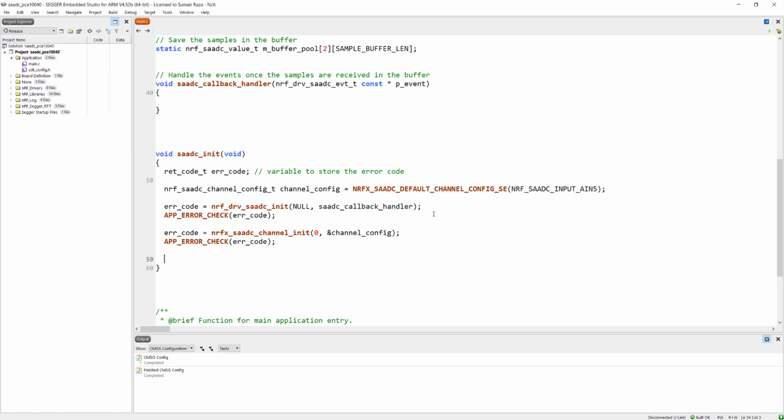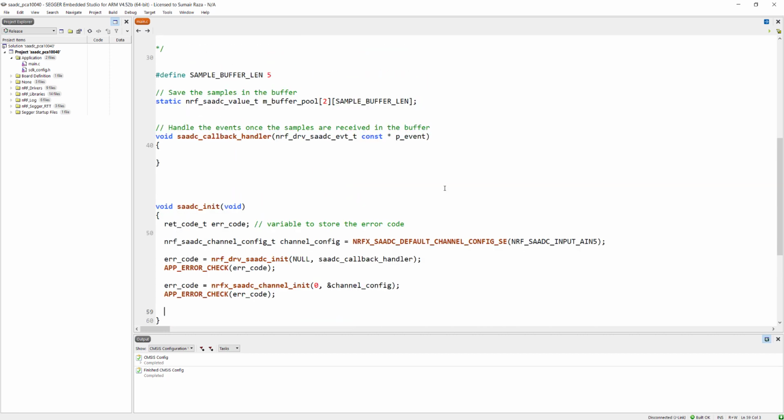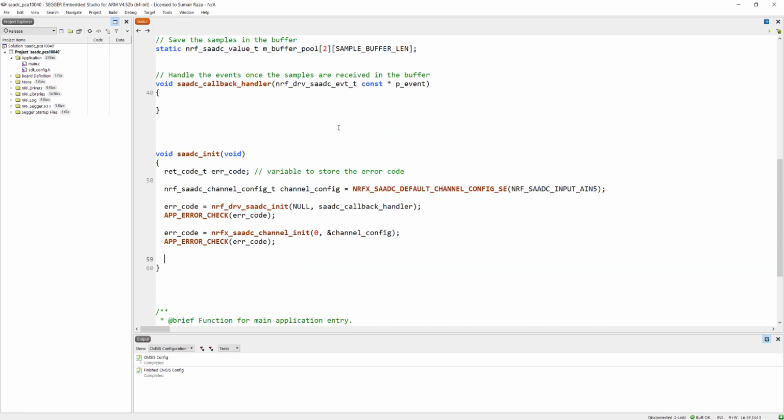The next thing I need to do is give the buffers. So we remember we have created a two-dimensional buffer. So basically we need a two-dimensional buffer, so the values will be transmitted to the first buffer, and if there are new values occurring, the previous will be transmitted to the second buffer, and the new values will be overwritten on the first buffer.